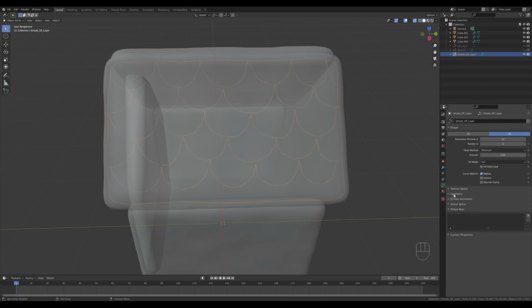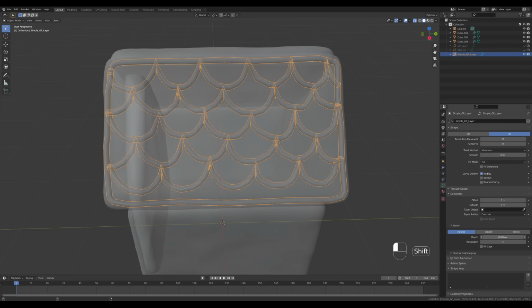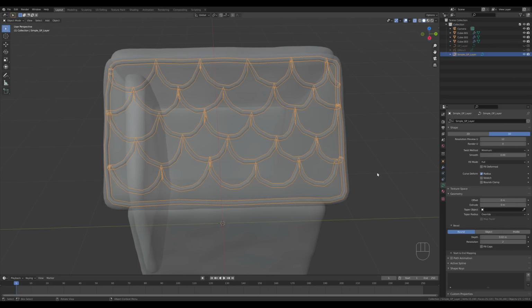And now you can just disable the original curve as well, and we have this simplified one, and we can go to the curve properties, geometry, and adjust the depth of the bevel. Now reduce the resolution here and apply subdivision modifier. So we can press Ctrl 1 and that'll make this nice and smooth. If you don't like these tips here, I recommend when you're doing your grease pencil painting, don't go continually, just go one curve at a time, so you will have them separated.